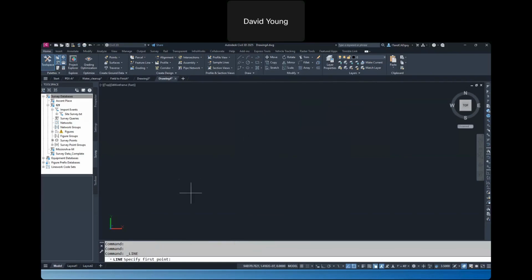So I'm going to pick a start point. I'm going to come up here. I want to go to the northeast. I want to go like maybe 70 degrees, 15 minutes, 23 seconds east. So I'm going to go to quadrant number 1.